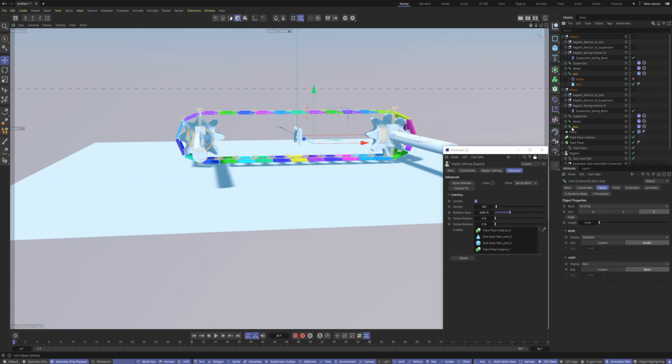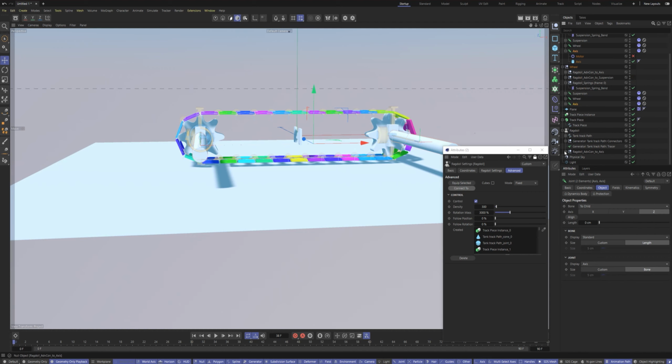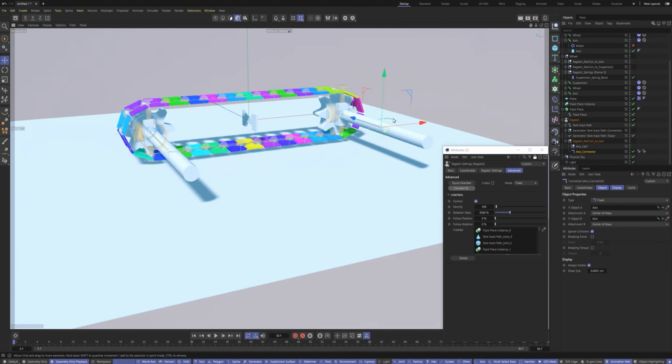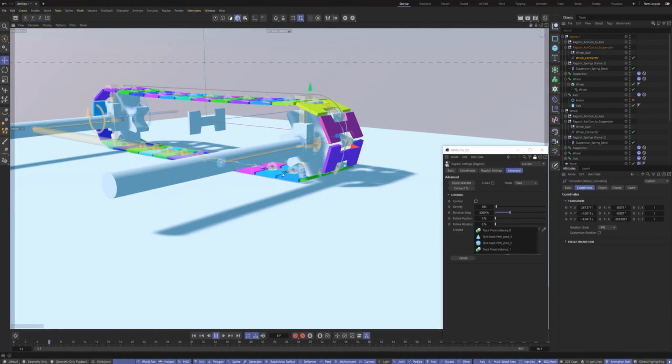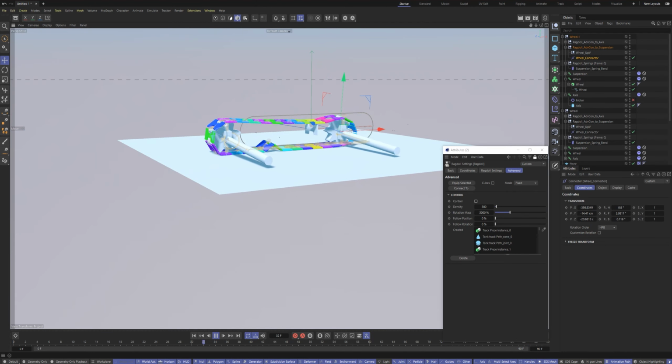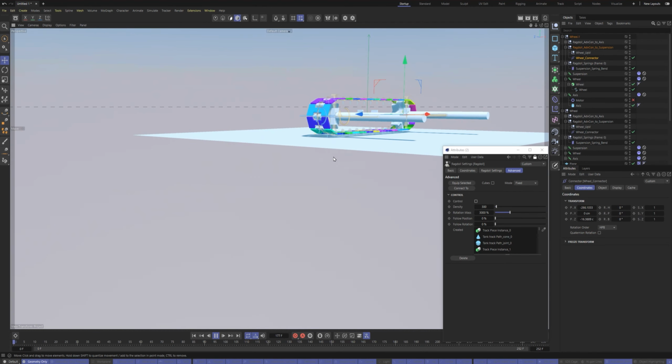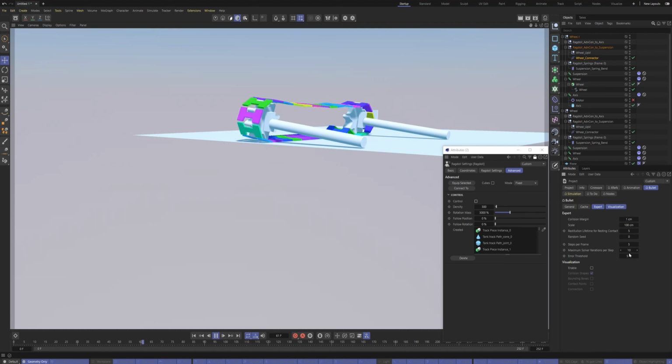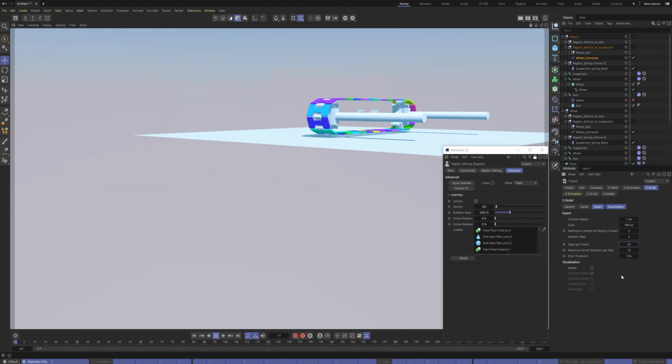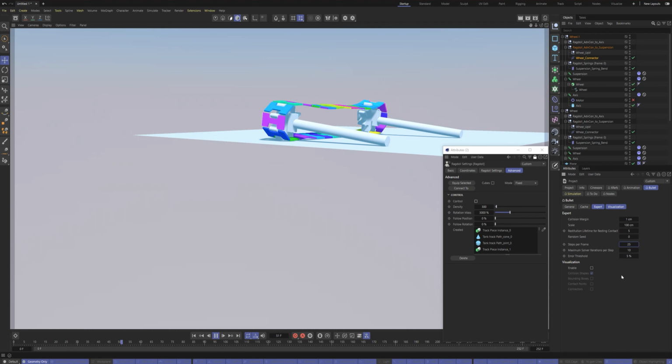Connect multiple axes with a connector in fixed mode to turn them into a rigid structure. The steps per frame parameter is very important during the simulation. Raise it to get more stable behavior.